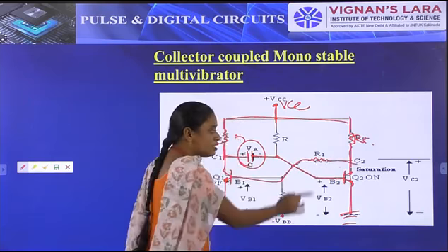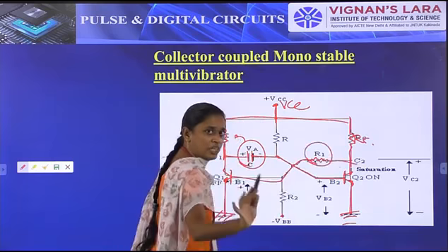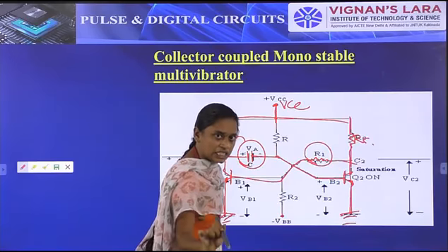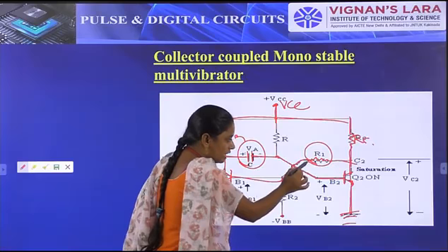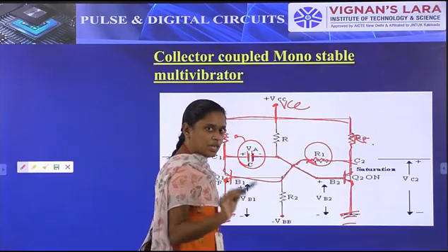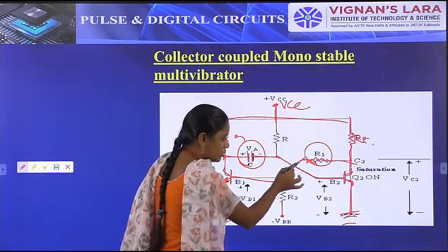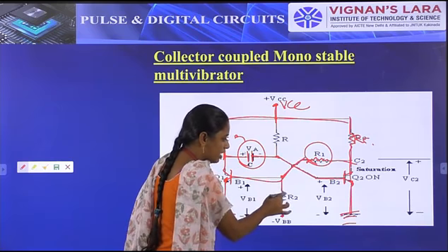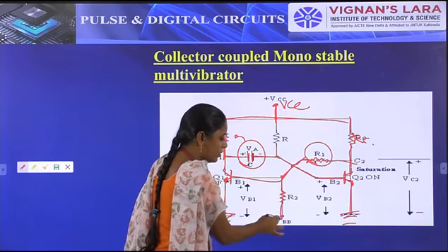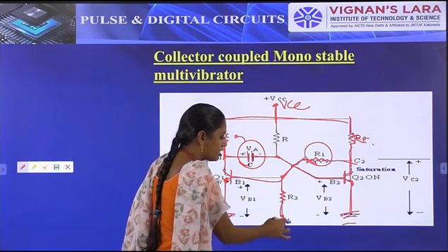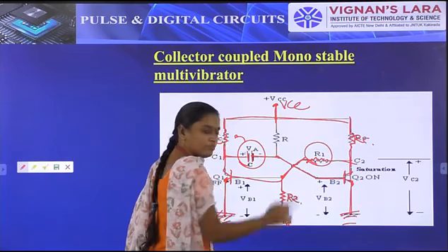In the case of resistive coupling, obviously we have to connect the biasing. So that is a major thing. In any resistive coupling, we have to apply the biasing voltage. That's why the other terminal of the resistive coupling will be connected to minus VBB, that is, the biasing will be applied here, and this one will be R2.